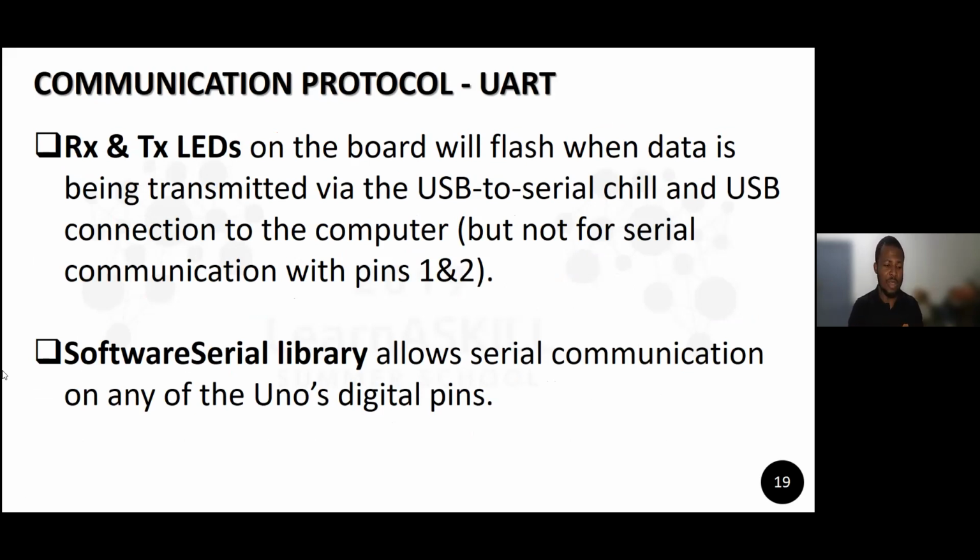There is a library in Arduino that comes by default called SoftwareSerial, and you can use it to make serial connections using any of the other digital pins to connect serially to other devices. But even if you connect 10 devices via UART, you can only talk with one device at a time. You can't push data to all of them at the same time. At every point in time, the Arduino can talk to just one. You select a particular serial port, communicate with it, select the next, and communicate with it.